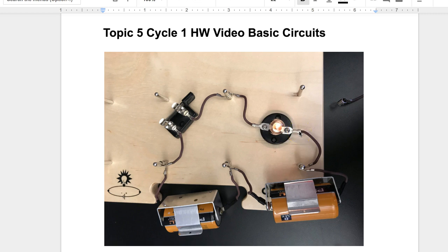So there are 2 probes on the voltmeter, one on either side of that bulb to see how much energy it uses. We wanted to see how to use the amp meter, the multimeter with the amp. We had to break the circuit. So if we did that with the real one, which we will be doing in our next lab, you'd open this circuit and then put one probe here and one probe here on the switch to make current go through the meter so you could measure how much current's flowing.